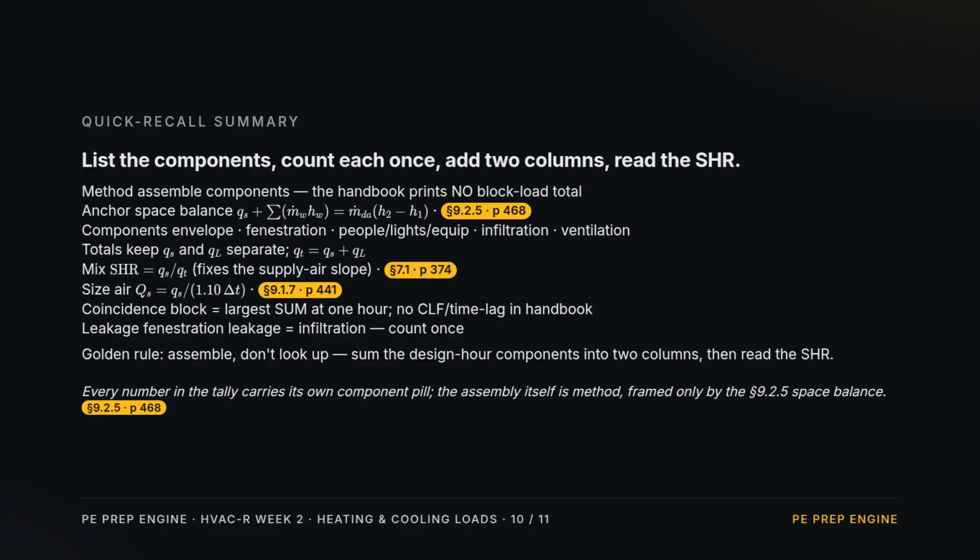Watch coincidence. The block is the largest sum at one hour, with no cooling load factor to lean on, and count leakage once. Golden rule: assemble, don't look up.